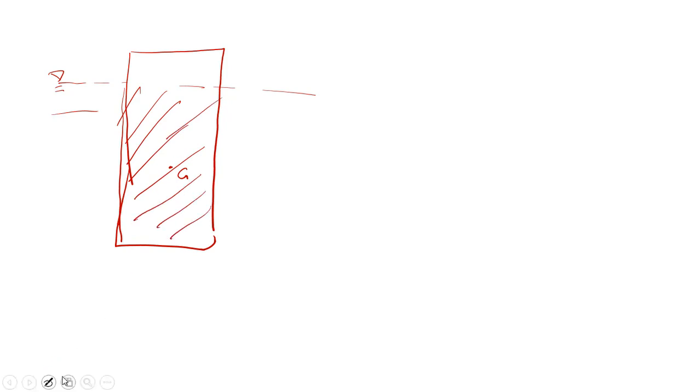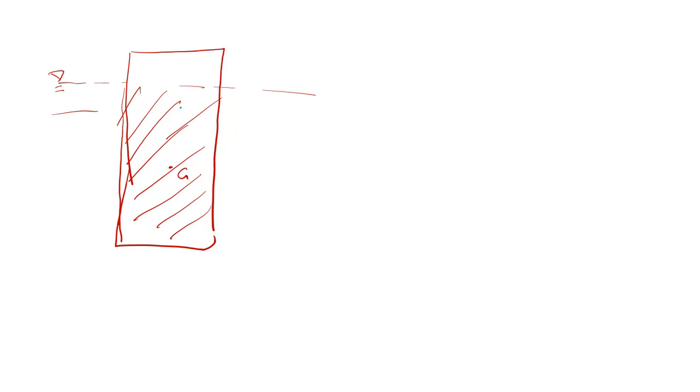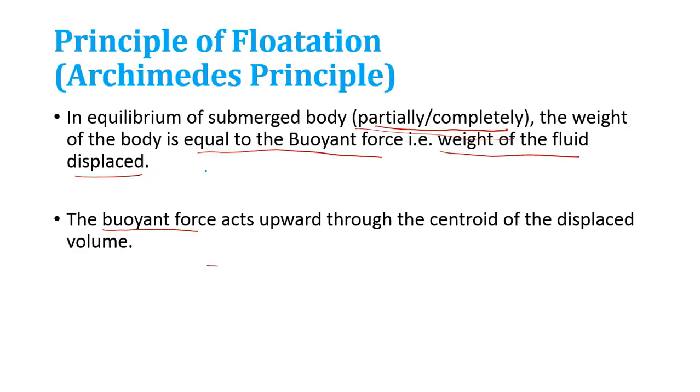So its centroid will be where the buoyancy force acts, somewhere here, the center of buoyancy. So from where the buoyancy force acts, it will be the centroid of the displaced volume. So this is the principle of flotation.